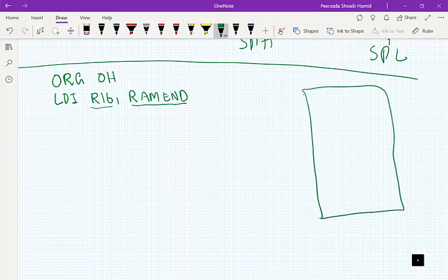This RAM end, as I have told you before, will return a 16-bit number, a 4-digit hexadecimal number. That means a 16-bit number, 2 bytes. But this R16 is only 1 byte long, so data will be lost. So what we do, we write something like this. LDI R16, HIGH.